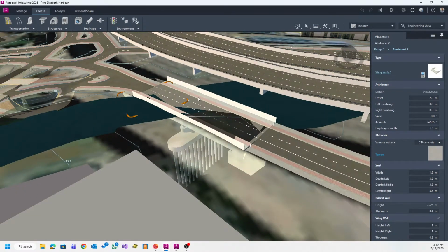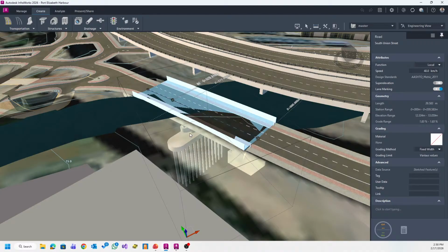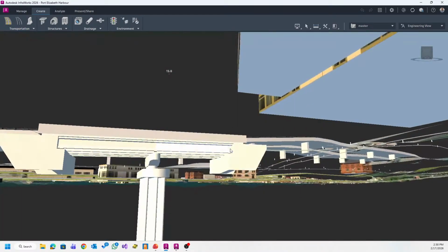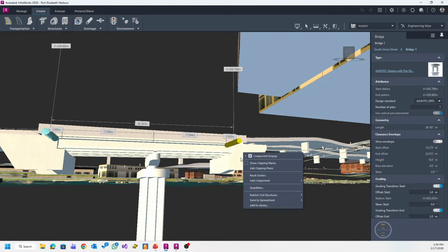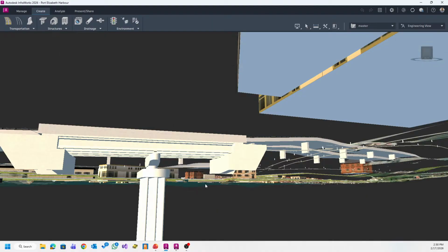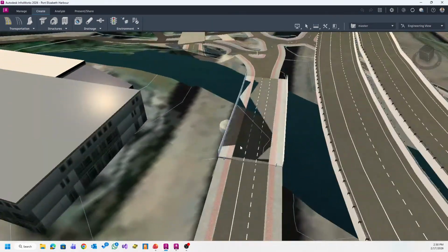And then from there, you can export this. So if I select the bridge, just sometimes a bit of a pain to select, but in that case, I've selected the bridge. You can, of course, change its name. I can then right click and I can publish civil structures. Okay, so very important. That's the process you need to follow. You need to then give it a proper coordinate system, so you can't just refer to LL84.